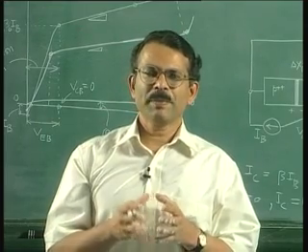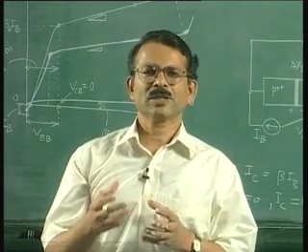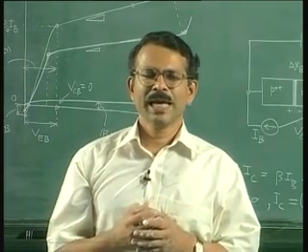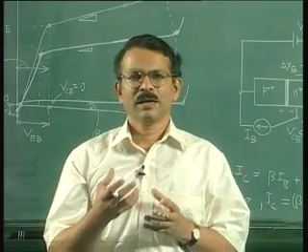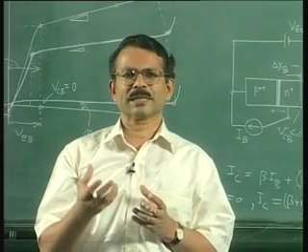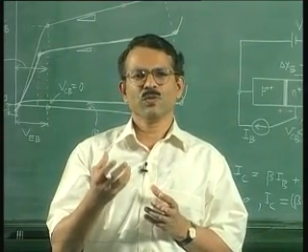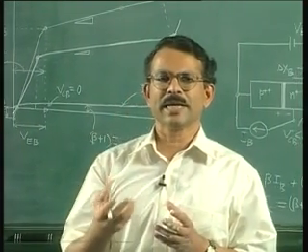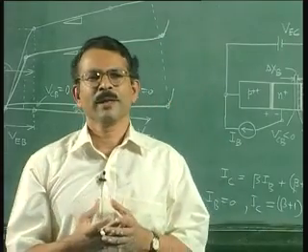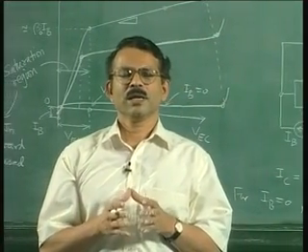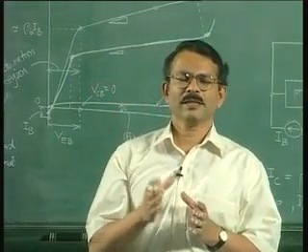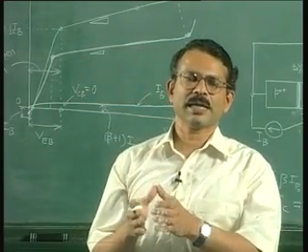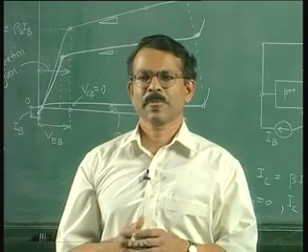That is why people say that the collector has got saturated with excess carriers when the collector base junction is forward biased. It is this large number of excess carriers for which we use the word saturation. So the collector is saturated with excess carriers, and that is why the word saturation. So saturation region, because the collector base junction is forward biased, and this implies large excess carrier concentration in the collector. Another way of saying the same thing is that the collector is saturated with excess carriers.